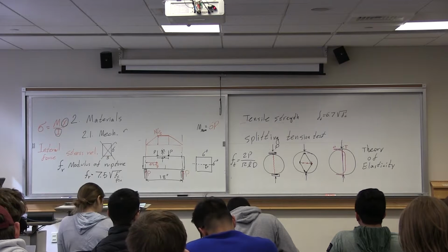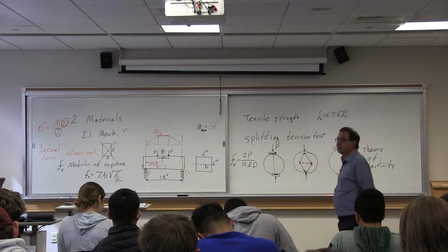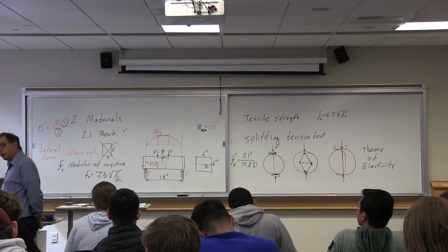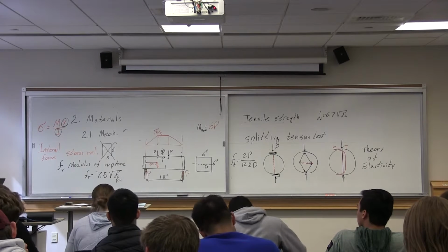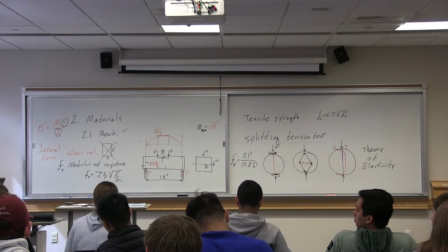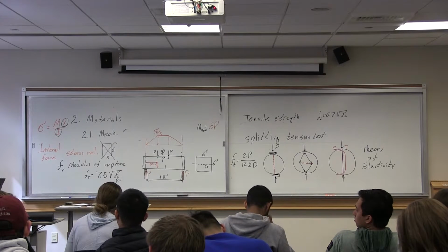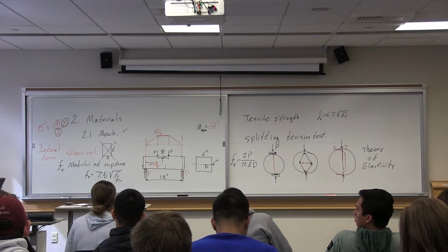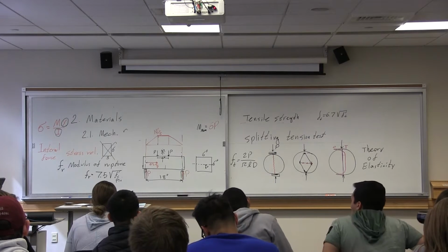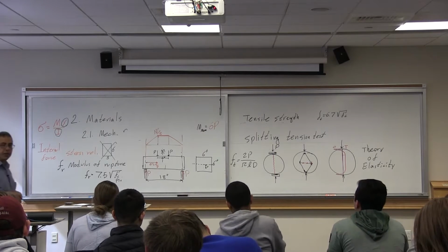Questions? Okay, so in the beam test we use modulus of rupture? Not in the beam test we use modulus of rupture; the beam test is used to calculate modulus of rupture. If you want to rephrase your statement: now that we found the modulus of rupture, in reality, if I want to look at tensile strength, which one do I use? I usually use f of r, not f of t. Any other questions?